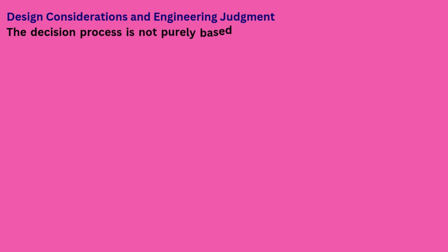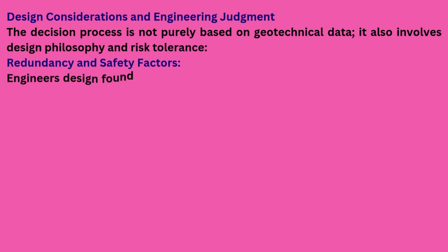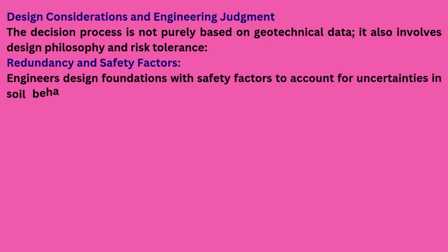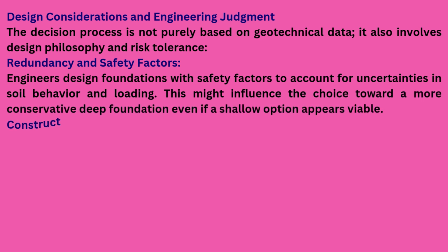Design considerations and engineering judgment. The decision process is not purely based on geotechnical data. It also involves design philosophy and risk tolerance. Redundancy and safety factors. Engineers design foundations with safety factors to account for uncertainties in soil behavior and loading. This might influence the choice toward a more conservative deep foundation, even if a shallow option appears viable.